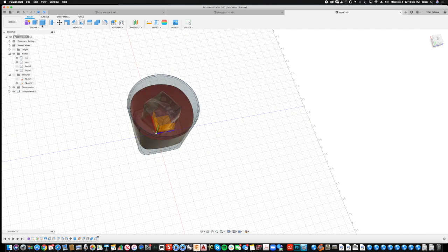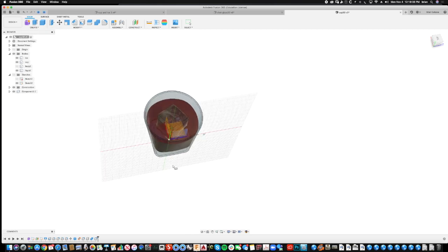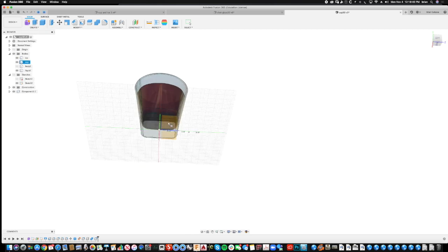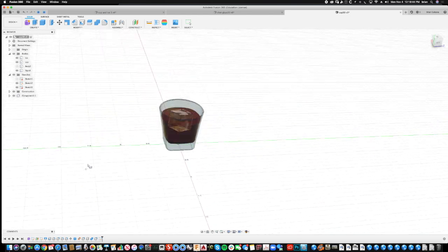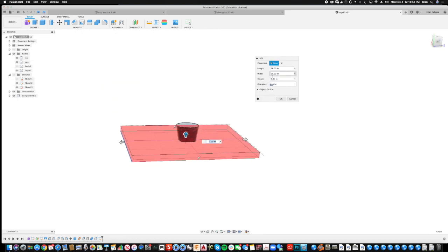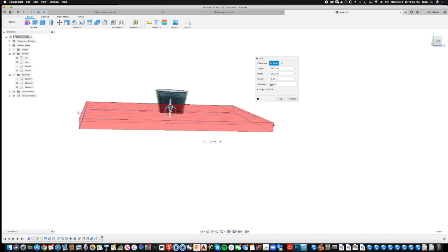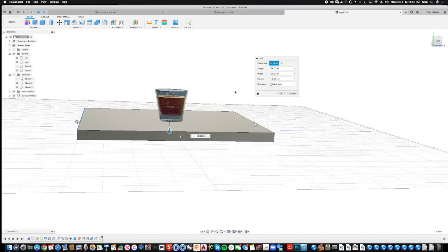And here I'll just grab this, or here, let's create a box. And we want to select that bottom plane, which sometimes you have to rotate around to figure out what you're trying to do. And then go corner to corner on the box. And we're just making the table. And it automatically defaults to going up. We just push it down. We don't want to join, we want a new body.